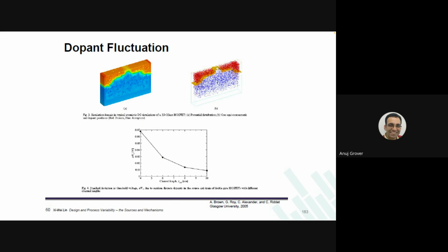It is not just the number of dopants, but all of them together and many more things which come as a part of random dopant fluctuations. Okay. Now, can you preempt? No. So this is truly random, and therefore you can only model it through Monte Carlo.